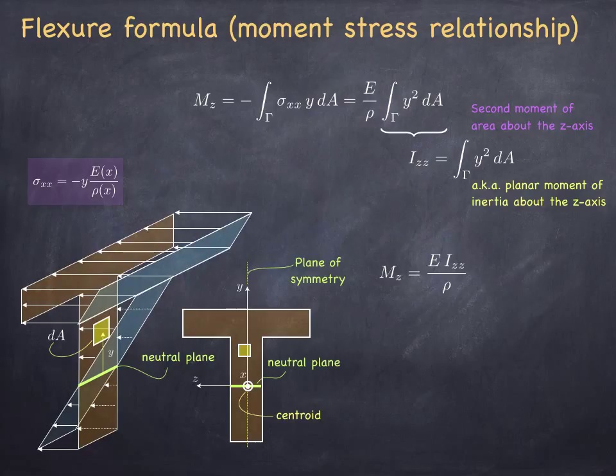So we have obtained a constitutive relationship that relates a measure of deformation, i.e. curvature, to a measure of forces or stresses, in this case the resultant moment. And the constitutive material coefficient here is EI. Unlike the material point constitutive relationship, which only has material properties, Young's modulus, Poisson's ratio, we have some geometric quantity seeping in due to the kinematic hypothesis that we have adopted.